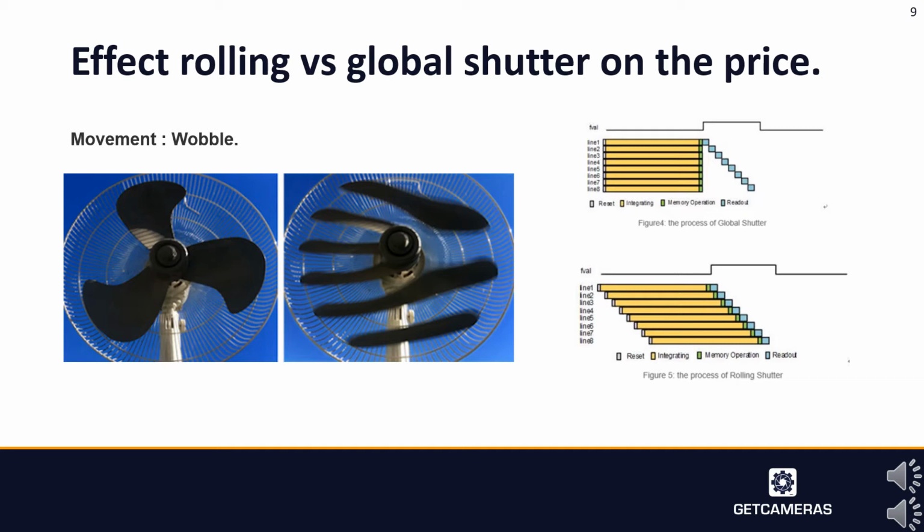And this blur, this effect will be more accentuated when the system resolution is high. So the smaller we want to see, the more important it is to cope with movement. For such reason, global shutter is always preferred. And thanks to modern techniques to produce the sensor, global shutter just returns sharper, crisper images compared to rolling shutter.